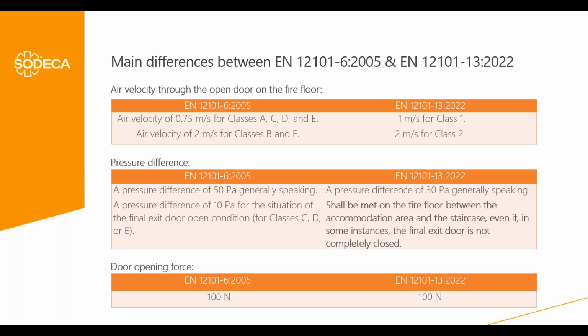In the new part 13, this 10 pascal requirement is not present, but there is a requirement that has to be considered. Because this door opens outside of the staircase, we saw that the self-closing mechanism tries to close the door, but due to the overpressure in the staircases, in some cases this door was not fully closed.